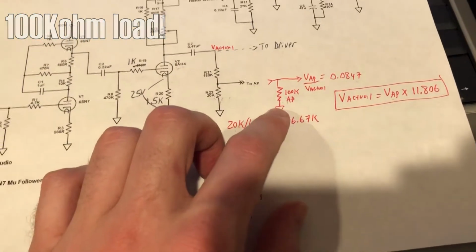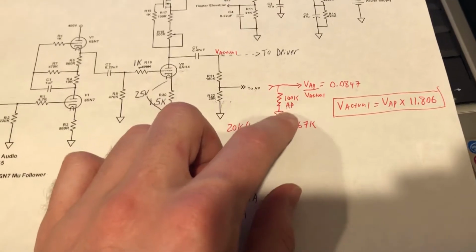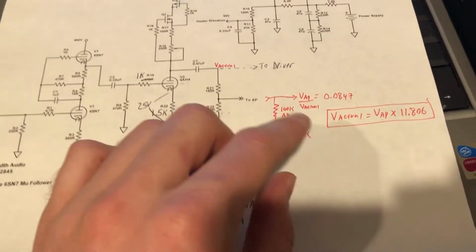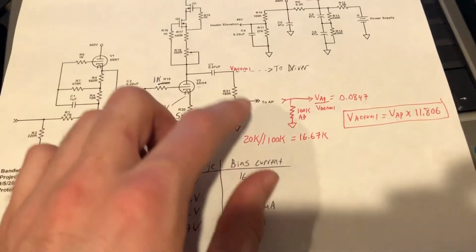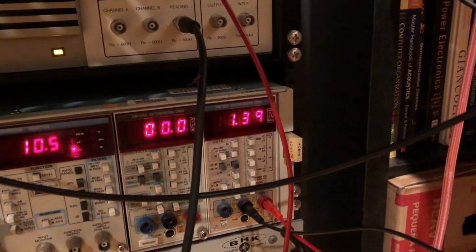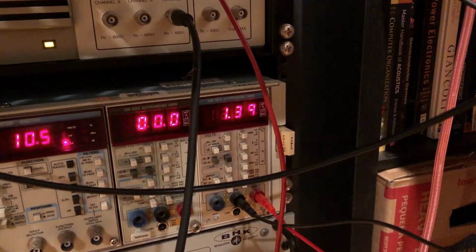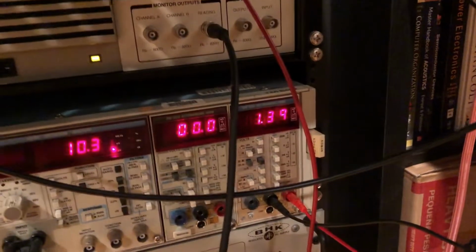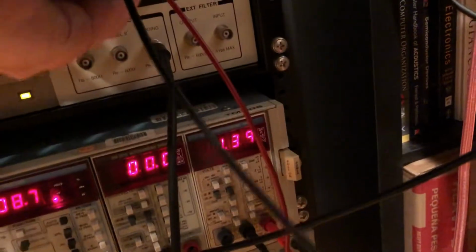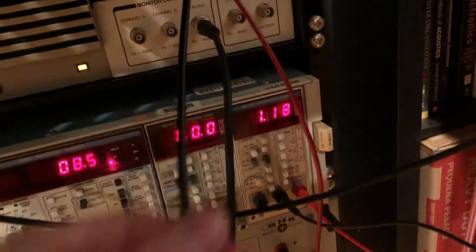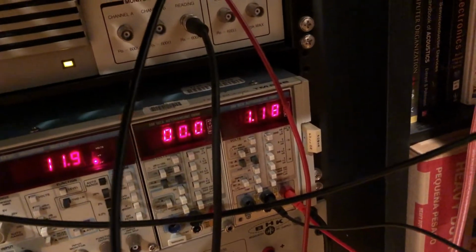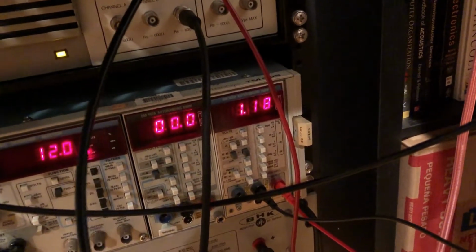And our digital multimeter, because it represents a 10 megaohm load, if we disconnect the AP and just measure with the DMM, we get our true 10-to-1 divider. So that number multiplied by 10 is now the true output voltage. If I reconnect the AP, you can see the AP is loading down the output and our voltage divider by that amount.